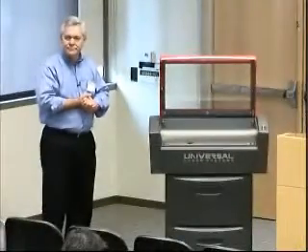The only other problem I've seen there is that the table isn't perfectly flat for some reason. Maybe the cutting table isn't sitting flat in the center. Then you might have it out of focus. That could be an installation issue, or it could get whacked and get out of level. The easiest way is to just check with a focusing tool in all four corners.